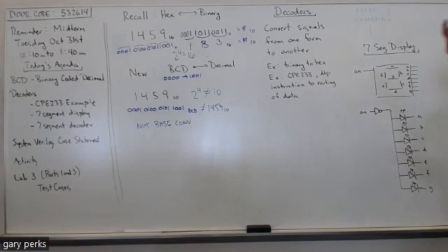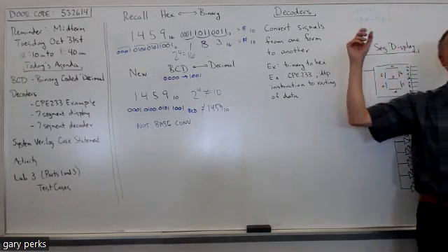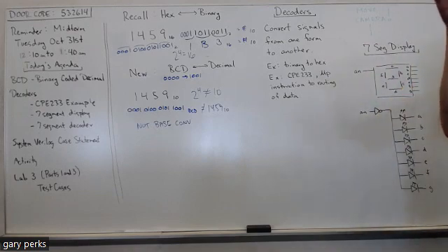So the decoder is taking in bits of an instruction and converting that into routing data, basically, through controlling muxes, through selecting. That's why it's called a control unit decoder, because it's controlling how the data flows.